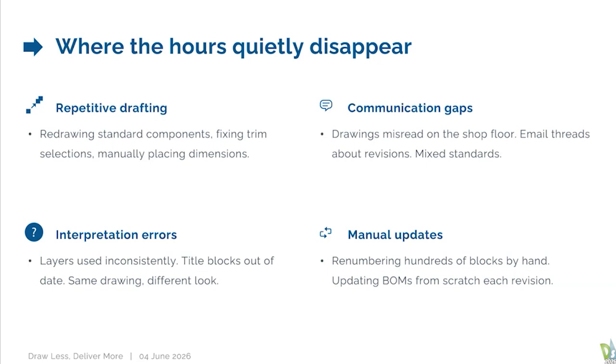There are communication gaps between departments, for example your design department and your production team. Then interpretation errors, where certain staff interpret drawings incorrectly. For example, if you use layers on your drawings, the draftsman understands that a line at this thickness means something else. In an electrical panel, if your line thickness is 2.5 millimeters, one would assume the gauge of the cable. If there is a miscommunication in how someone interprets that drawing, they can end up wiring the panels with the wrong wire.